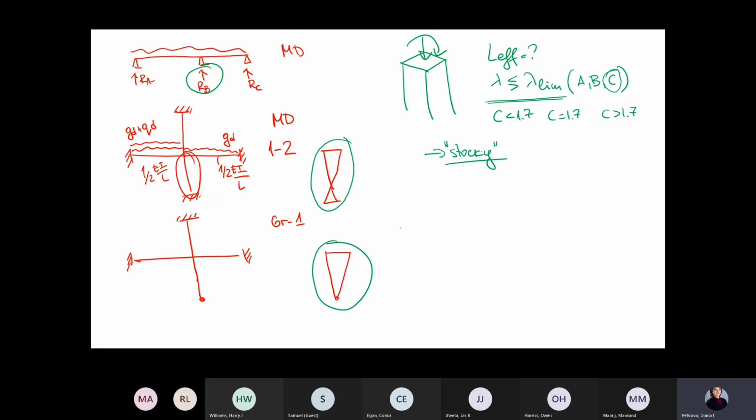I think the example they have in the guide is probably 300 by 300. If you're doing the column from the ground floor to the first level, I would start with 350 by 350. Okay, for maybe level 1 to 2, I'll go with 300 by 300.